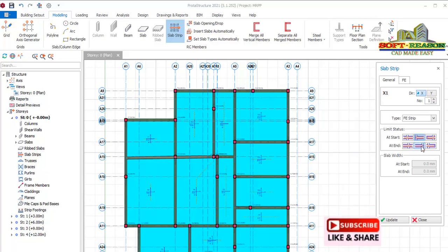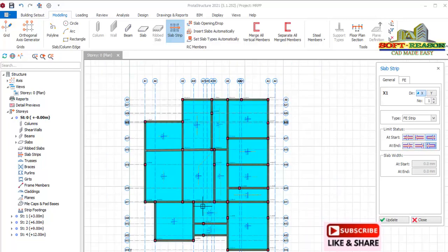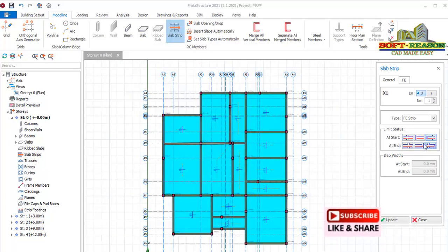Choose it properly. This place is slab, and here is, sorry, this is raft, meaning you are starting from outside and ending outside. So now this provision is slab, meaning you start your strips inside the slab and you are ending it inside the slab. That's when this provision can be selected. Here is cantilever. Here in this provision we have cantilever, so there's no need for these other options. So for the middle options, you will be considering this one, slab, raft, which is outside.